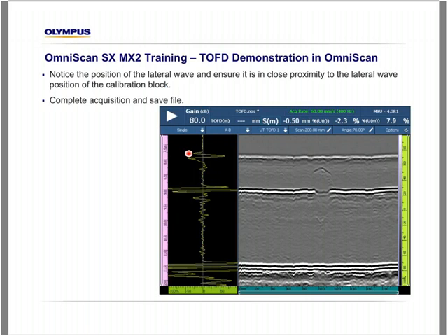If the arrival is within a half a microsecond or maybe a little more than that as the calibration block, in other words, if this signal's arrival time at 7.5 microseconds is the same or very close as the calibration block, it's telling me that the surfaces are flat.